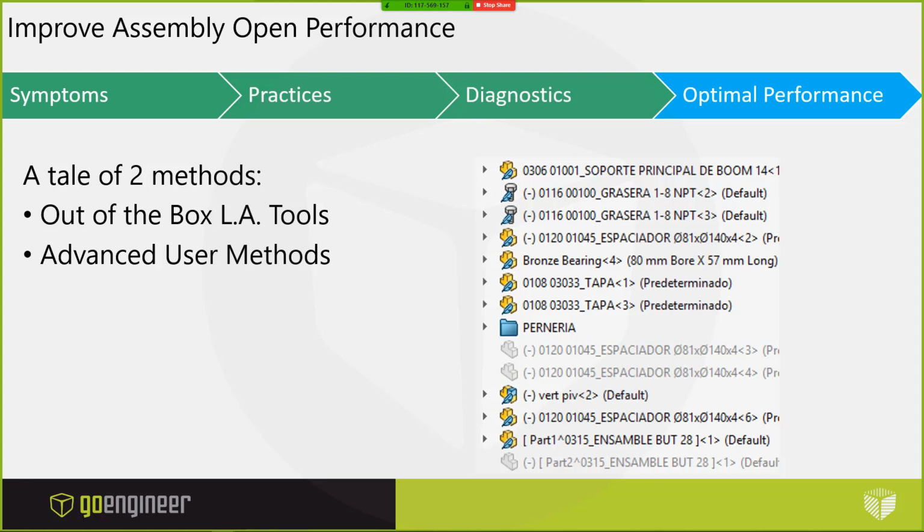This is the default state in SOLIDWORKS, and it fully resolves and takes a look at all of the different parts of the geometry. Then there's lightweight mode. Lightweight mode only opens up a subset of the model data, not the full and fully featured models.